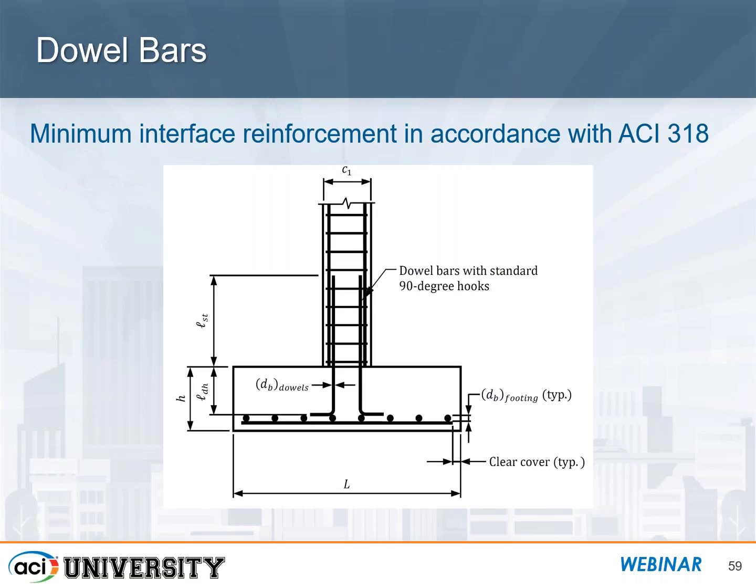Okay, a couple more questions. Tenny wants to know, in a shallow grade beam supported by piles, can we bend the pile reinforcement, she means with a 90-degree hook? Oh yeah, you mean to develop it into the grade beam? Certainly. You have a shallow grade beam, that's fine, as long as you have enough development length.